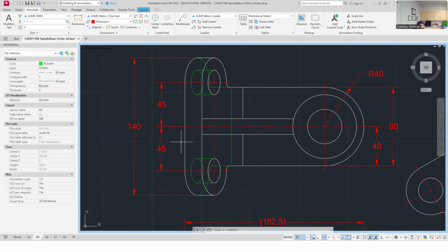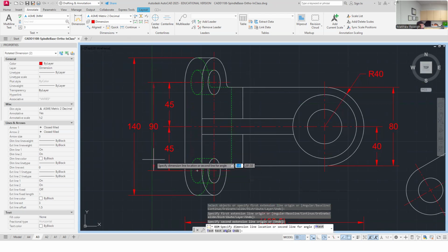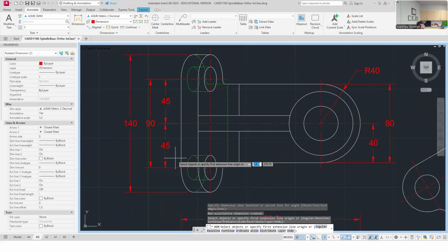I could add them between each other, right? It's still not double dimensioning to do. Sometimes you'll see me do this, that I might say, well, yeah, it's 45 over from that to that. And then it's also 90 over. This seems like it's redundant dimensioning. And sometimes when the math is easy, it does look very redundant. But if the math is trickier, then this is not super redundant and it's actually a helpful dimension. And it's not a double dimension, unless I do it twice, then it is a double dimension. But just that one right there.